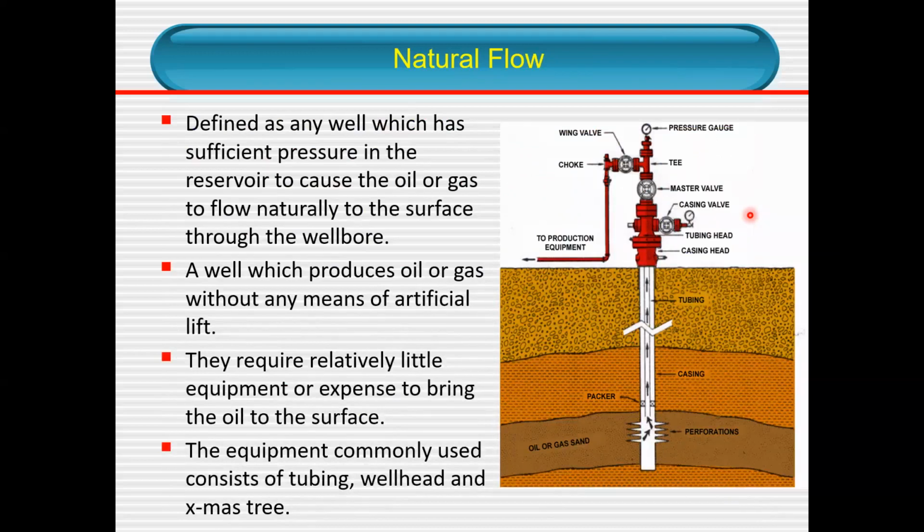When you have enough pressure, you are not worried about any kind of artificial lift or gas lifting, because of the enough pressure in the formation or reservoir. Once you put the casing and tubing into this reservoir, it can flow on its own independently without any assistance from the gas or even a mechanical pumping unit or anything. But how long are we going to sustain this natural flow? Maybe a few years, 2 years, 3 years. In fact, if it is really clean, it can last like 5 years, 6 years.